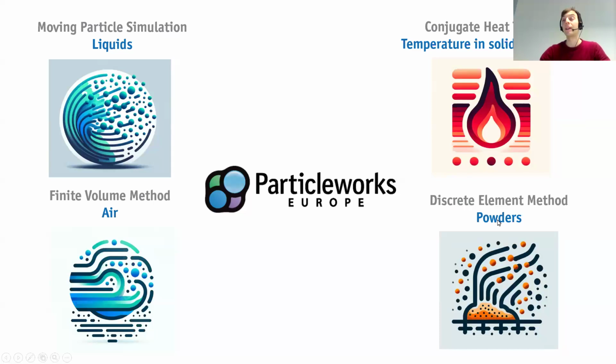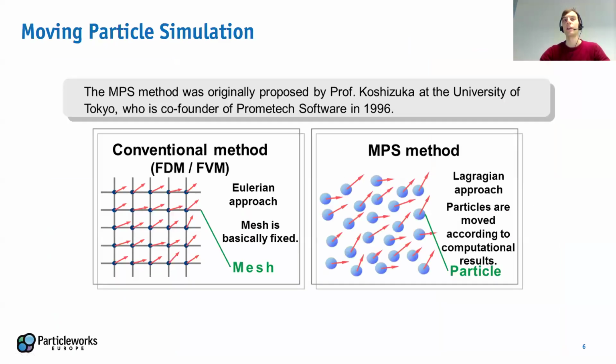We have the possibility to integrate also powders or solid materials with a discrete element method solver. And we can also predict temperature in the solids with a conjugate heat transfer method. And we will highlight these modules later on in the presentation.